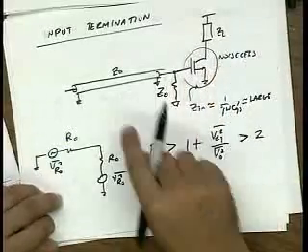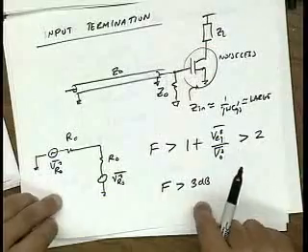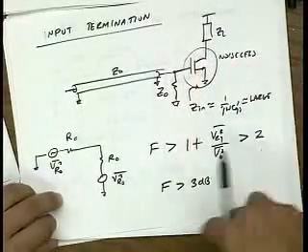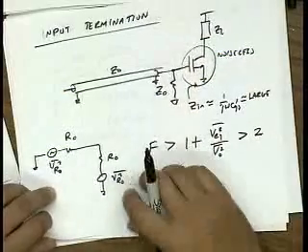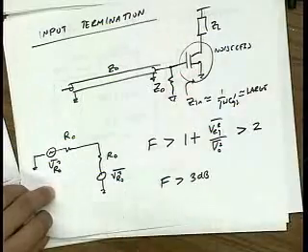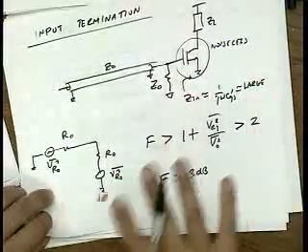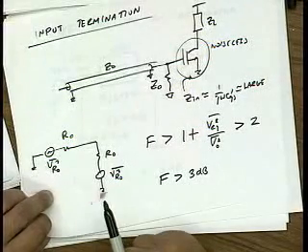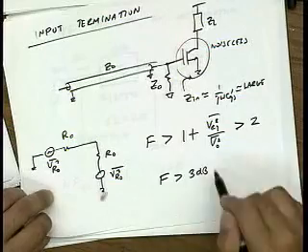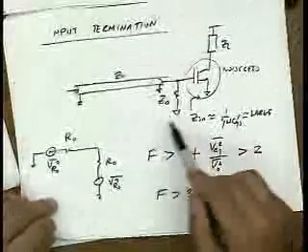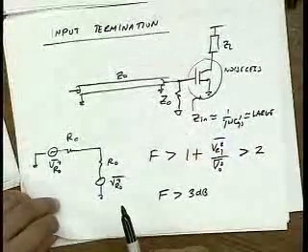So if this is 3 dB and you add another 3 dB, you're at 6 dB, and then you add the noise of the transistor plus the rest of the circuit, pretty soon you're up to a noise figure well over 10 dB, and that's unacceptable. So in order to maximize the communication rate, you have to minimize the noise figure of your system, going back a couple lectures. Typically we'd like to have noise figures that are less than 2 dB. Okay? So something simple like this is very elegant and simple, but unfortunately the noise figure is just too high.